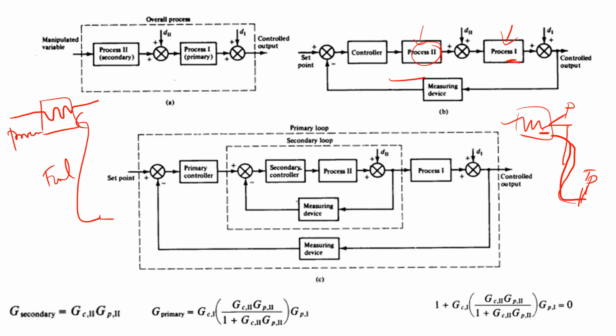So here, what you do is take a measurement of this. So this is a flow transmitter. This is given to a controller, a flow controller. For this, take a temperature measurement, that is given to a temperature controller. This is the set point, and this is the process variable. Then the control output is given to the controller. So this is how it works.